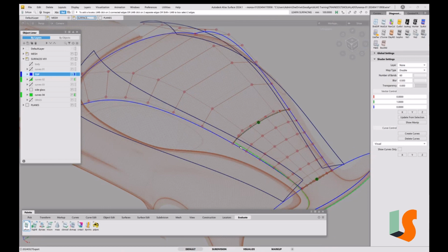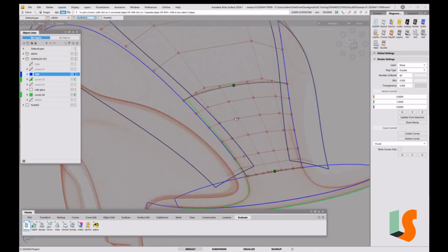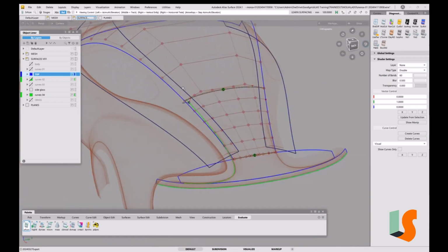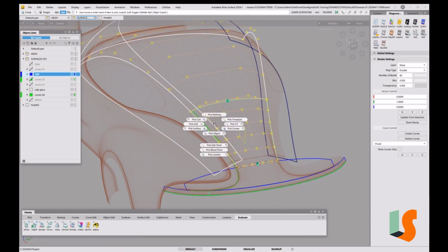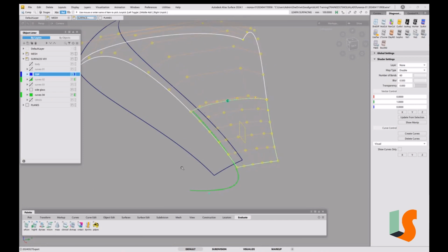So this curve here, I originally did from the edge of the surface, and that's actually not quite right. I actually want to make that aligned to the intersect with these surfaces. So let's get those surfaces and that curve there. Just isolate that. So we'll go into here, and then we want to go and intersect the two. It's a bit weird, really, but it's under surface edit because it's associated with trimming and everything. But that's where intersect is. So intersect. Well, in general, we do want history on, to be honest, but I'm not planning on changing anything.